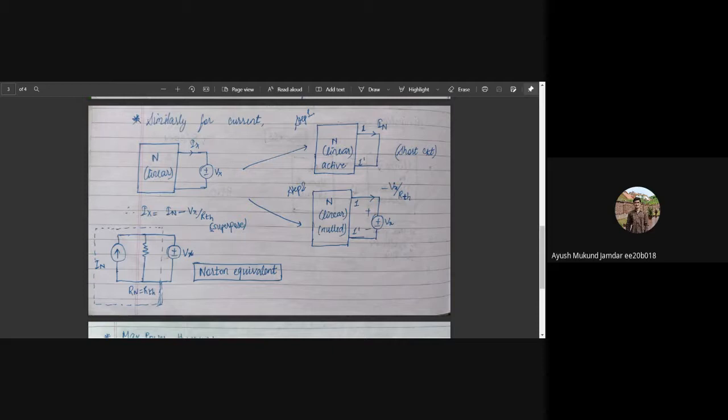And we put up, let's say, a voltage source across the terminal, that was Vx, any Vx. Now there will be a current going through it for the Vx as we have applied. So we can measure the resistance across it, again measuring the I and V parameters at the terminal. We'll get the resistance, that is RTH, just as in the Thevenin case.